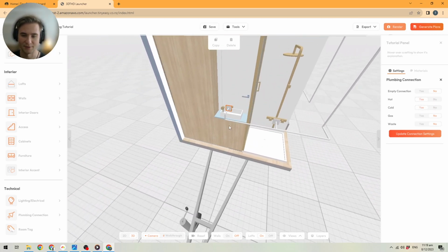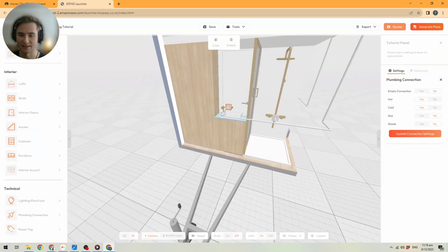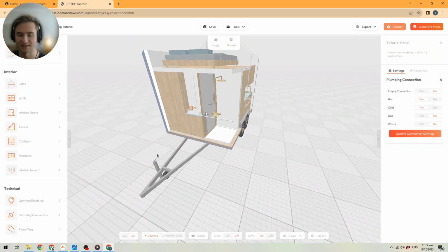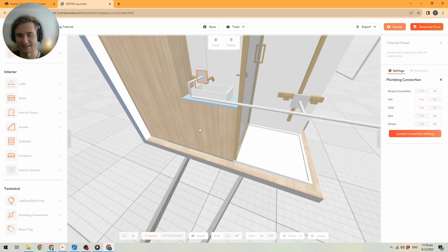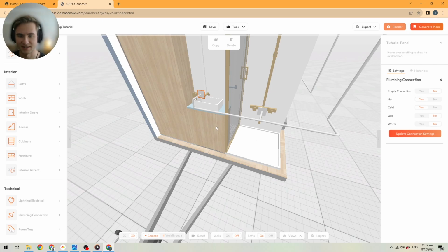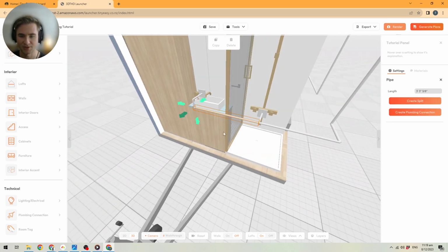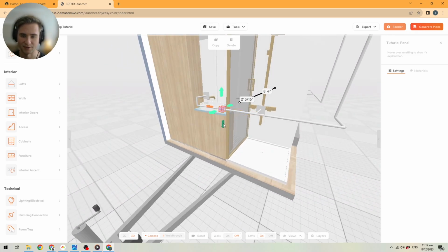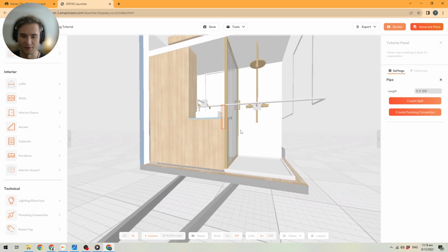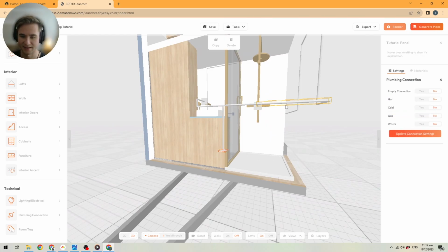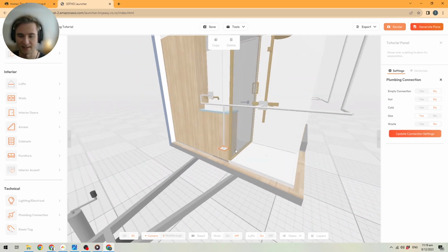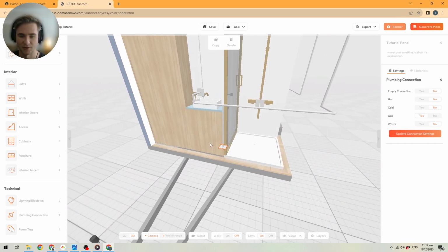And one other thing that I want to do is I actually want to be able to connect a gas bottle to this system. And to do that, to just create a connection that's coming in, you can just take one of your pipes like that, create a split. And then what I'll do is I'll just draw a pipe going down like that, and I'll just create another plumbing connection that leads into nothing. And essentially that is now my gas in, so that's where you can connect your gas bottle.